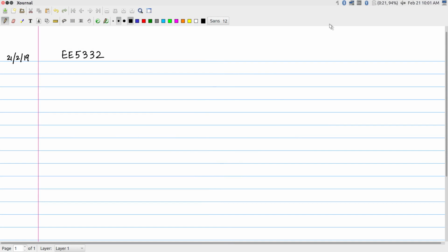Okay, so yesterday we were looking at the idea of resource sharing, and in particular the approach that we are taking in order to implement resource sharing is a technique that is sometimes referred to as folding. Right? The idea being that you have a set of operations that need to be completed and you have a finite set of hardware resources. You are going to fold multiple operations onto the same hardware resource so that the hardware resource can be time multiplexed, and over a certain number of clock cycles will finish all the iterations required and all the operations required to complete one iteration.